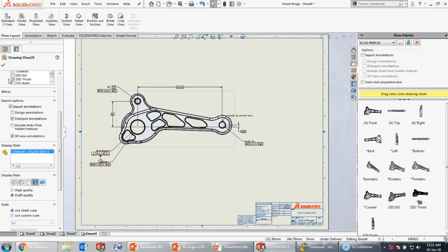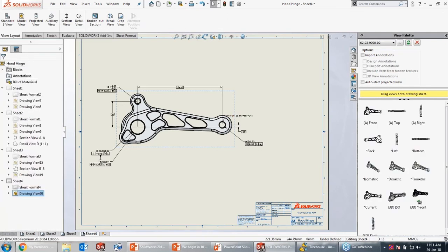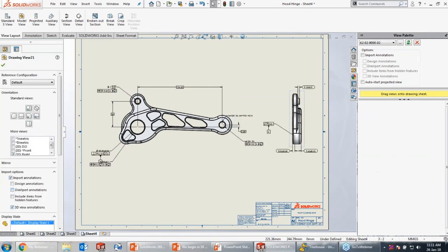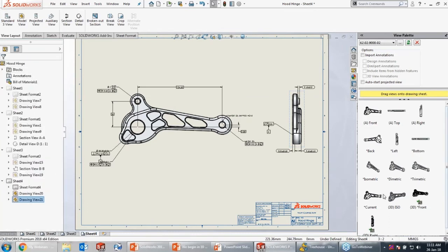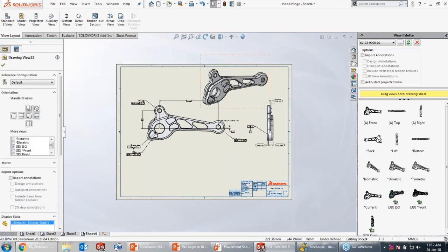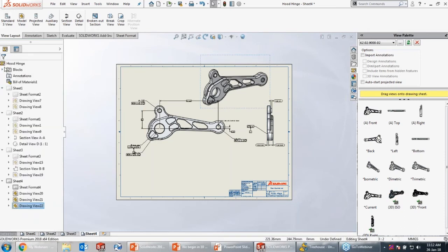So we're discussing something about a hole callout. In SolidWorks, we have something called an advanced hole, which lets us create stepped holes very easily. Adding annotations to the hole callout is very easy, and hole callouts can be easily added to the stepped holes as well. This new feature lets us switch the near and the far side in the annotation, and the order of the callout can also be very easily reversed.